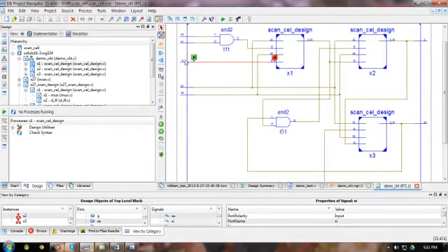Now I apply a scan input, let's say 1, and make scan enable equal to 1, which means it is in the cascade mode, the scan mode. And immediately when I apply 1 clock cycle, what happens? The scan input of this comes here, the output of this comes as the input of this. Indirectly, when the flip-flops are in cascade, they act like a shift register. If I apply 1 here and apply a clock, that 1 appears as output here.